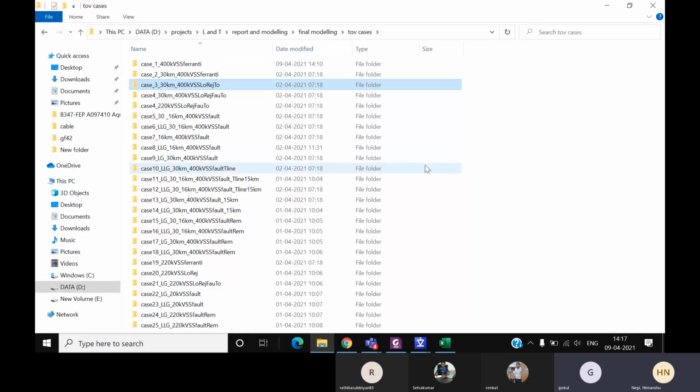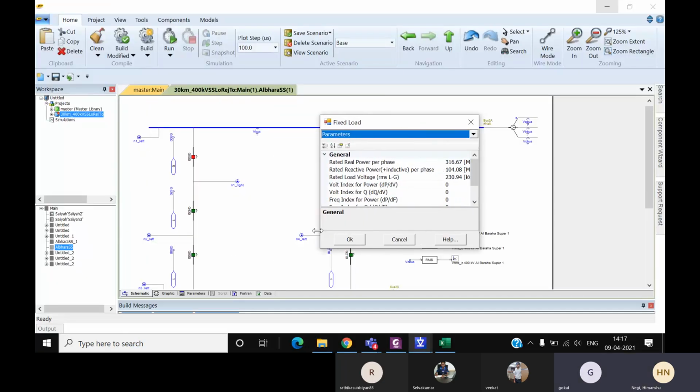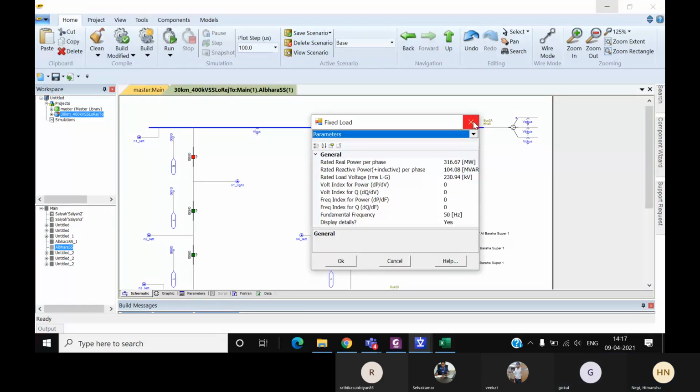The magnitude of load, how do you select that? Just from the transformer data itself, or from a client email? How much load you want to reject? We took 500 MVA itself, the transformer load. We just took that 500 MVA and rejected that load. Okay, so this is per phase, right? Yes. That we have to get from the customer, Himanshu.